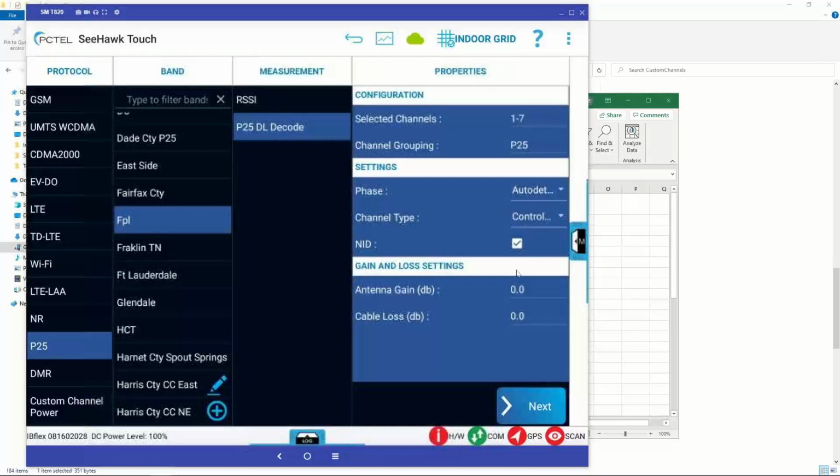Yeah, that would be helpful as well. When they were testing out the simulcast system, the way they did quasi testing of a building is they would roll up next to the building and put like a 10 dB or 20 dB attenuator on their antenna. And that supposedly simulates, with quotation marks, the level in the building. So is that something that could be done here as well? You could.